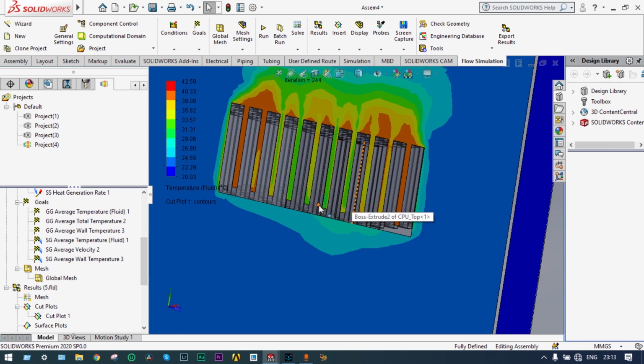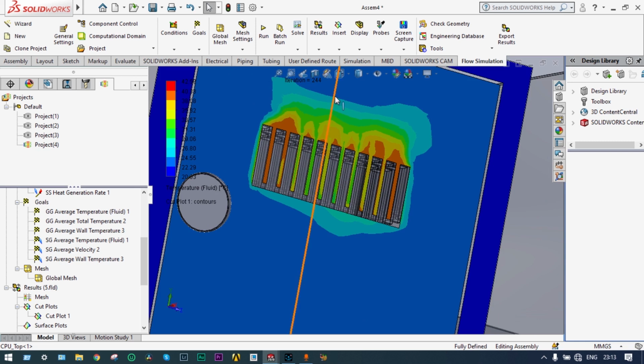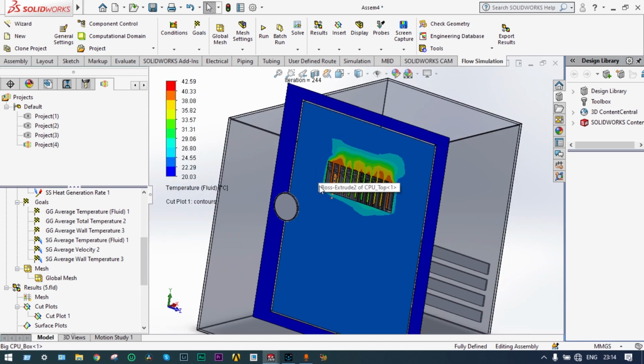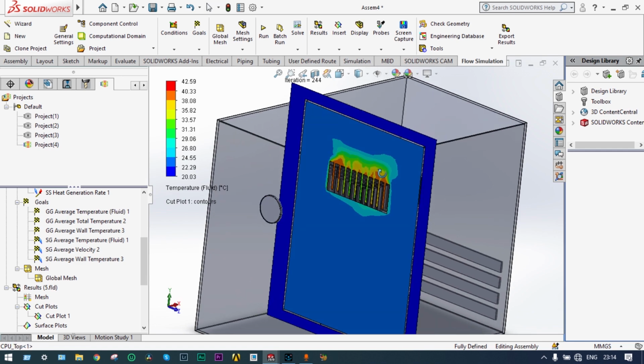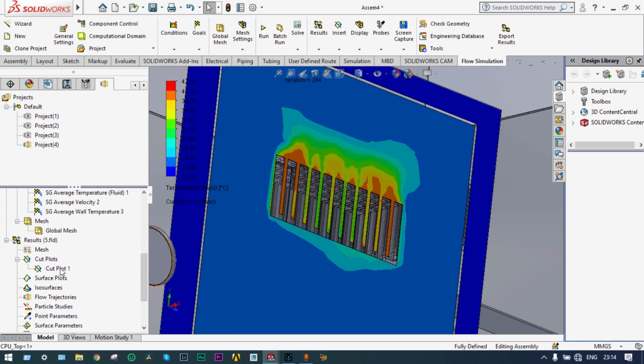You can see the temperature at the top end is a little high. So actually, as it is going up, the temperature of fluid is decreasing near the fins, because conduction is starting from the bottom only, and as it is going up, its temperature is decreasing, and at the airflow also, because of the convection, as air is flowing from the left hand side, its temperature is decreasing. You can see this one properly. Now see this flow in the form of an animation.